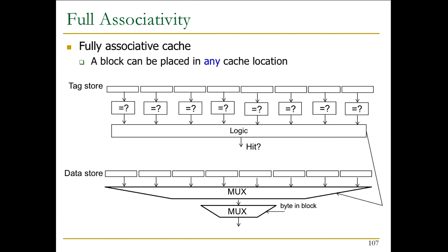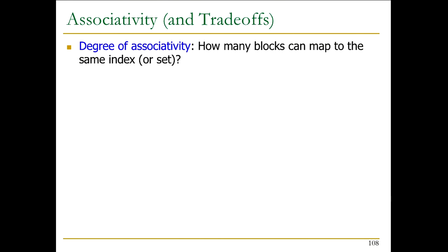Now I'll ask you the question, does higher associativity always lead to higher hit rate? That's a trick question again. And the answer is no. Not surprisingly, but you can construct an example when higher associativity actually leads to the same hit rate, easy, but also lower hit rate depending on the access pattern and the replacement policy. But we're not going to talk about that right now. That could be a homework question, actually, if Juan reminds me of it. Or maybe you can now start thinking about it. You don't believe me, maybe. That's okay. Now you can prove it.